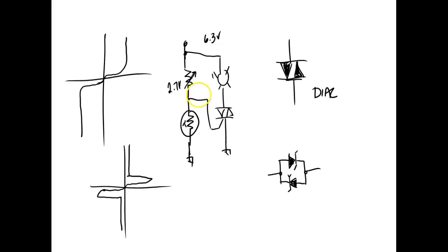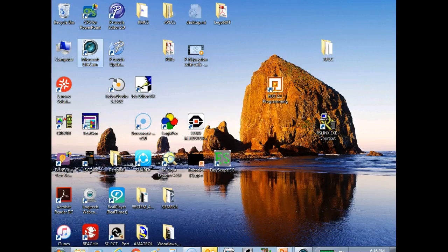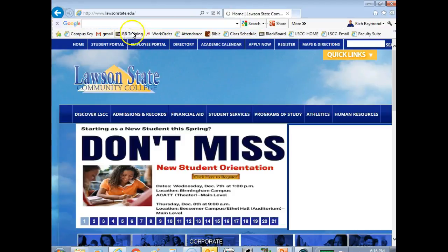So what happens if I come over here and put that diac right here? For one reason, now we're going to be able to control when it breaks over, and we'll fire it at the same voltage every time. So if we look at some triac firing circuits, odds are they're going to show a lot of diacs.